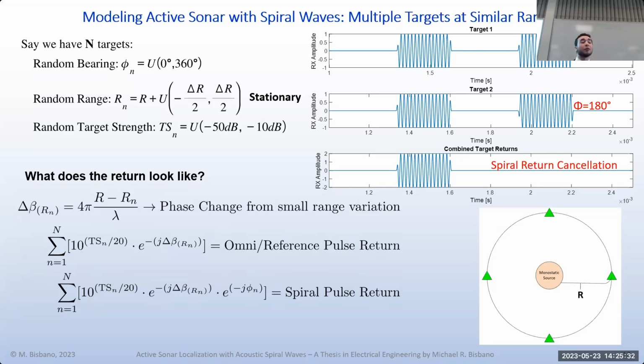So there's definitely some interesting effects here. And really, this limits your processing. Unless you get really complicated with it, you're really limited to only detecting one target per range bin. And I'd say the range bin is on the order of the entire pulse train's length. So if you're doing an omni, then a spiral, then an omni, the entire duration of that needs to be your range bin. It's dependent on that, not the order of one individual subpulse, but the length of the entire pulse train.